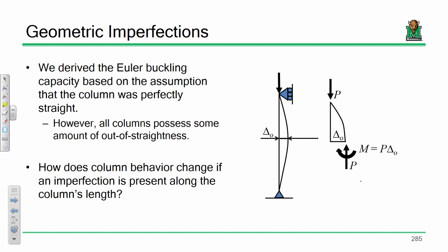Now, are we talking about beams or columns, just to be clear? Okay. No, this is a fair point. Let me say this. You're never going to get something that's perfectly straight. Now, when would you ever order a beam that's perfectly straight? The simple answer is when the dead load deflection is just really tiny. Like if you calculate the dead load deflection and it's only like 1/10 of an inch, don't worry about it. So that's a good question. But yeah, with columns, we don't want them to be imperfect, but they are.